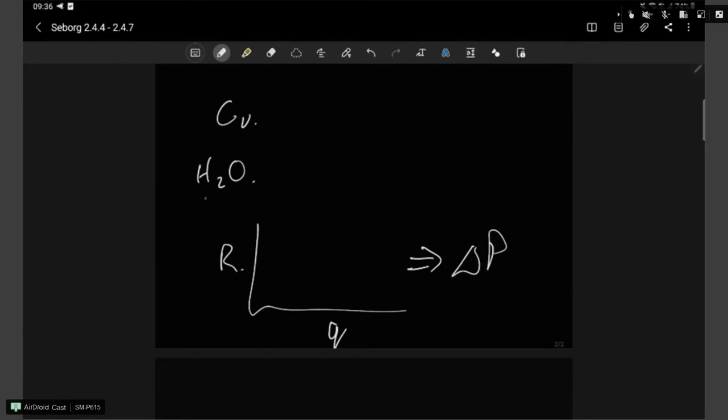Now, the first thing that you should note is we are using water. Water, obviously, because it's one of the most abundant liquids that we have around. So it's easy, it's cheap, it's everywhere. We can use that to determine all of these characteristics of our equipment. But water has got a density and a viscosity, and the CV is not independent of those two. It will have some form of variation depending on a different viscosity, depending on a different density.